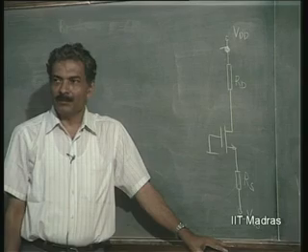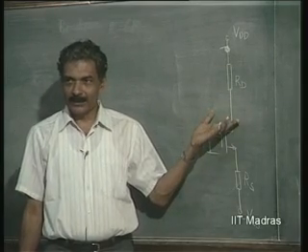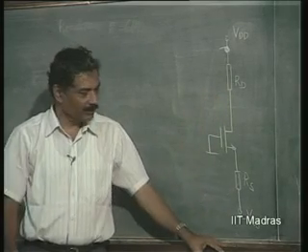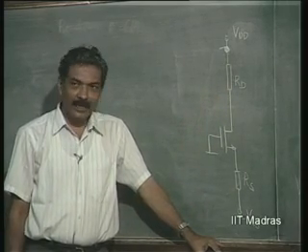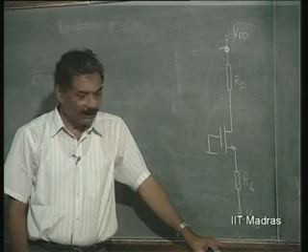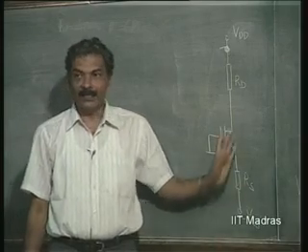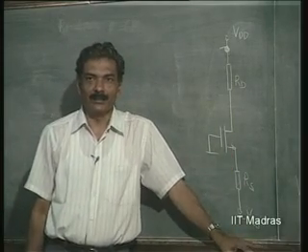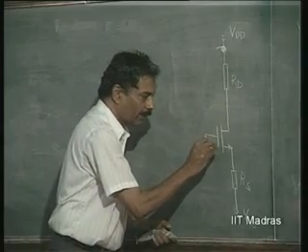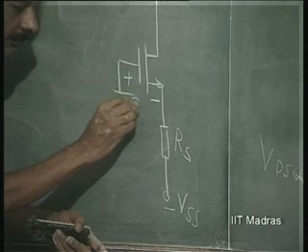In the case of bipolar junction transistor, we started with dual supply and went over to single supply. In this case, we have started with single supply and are going over to dual supply, just to make you understand the basic concept properly. If you are given the choice of biasing this using dual supply, then we will fix the current using RS itself here. So, it is very simple. Now, for the same problem, this should be 2 volts, we are told.